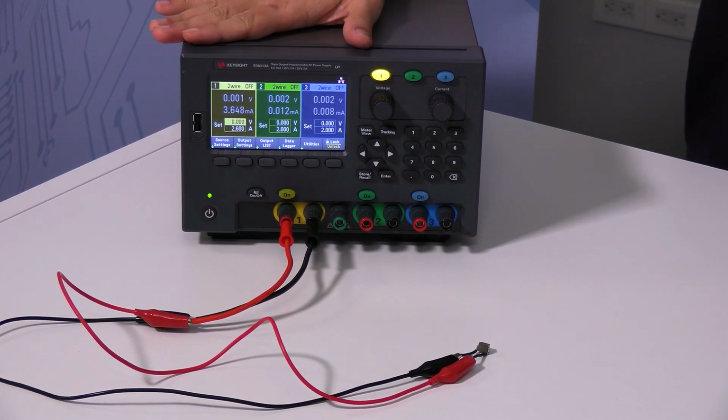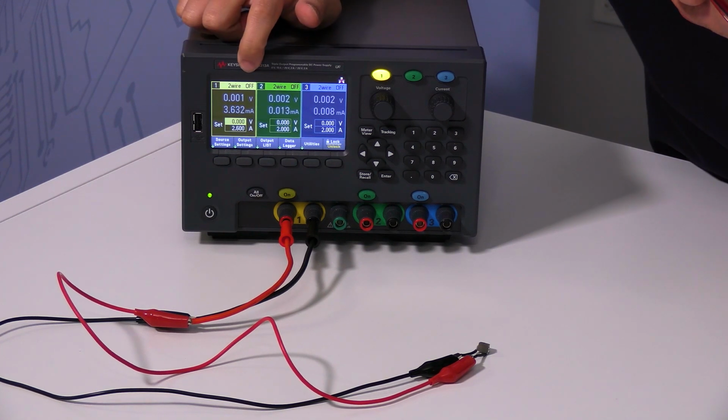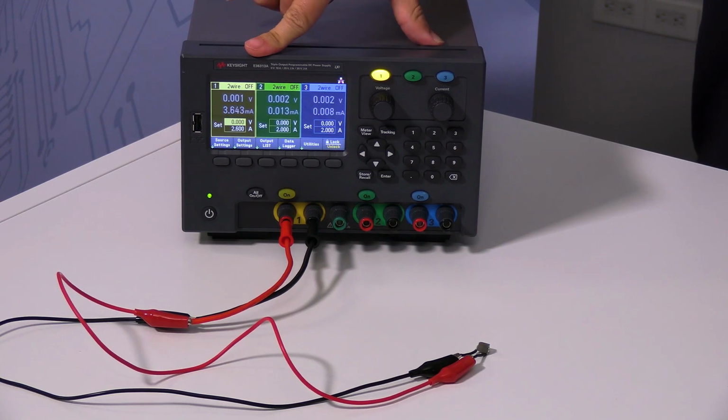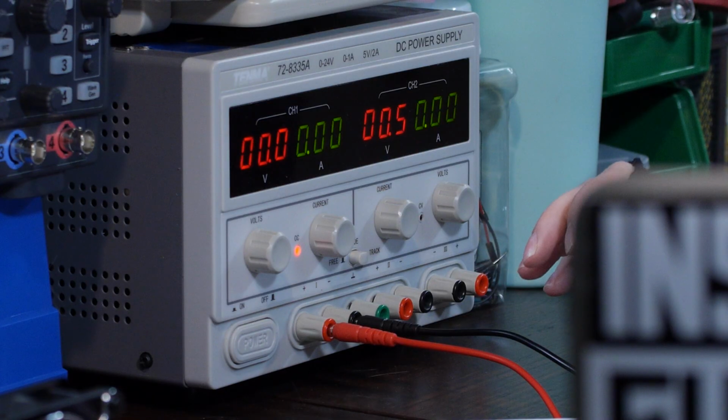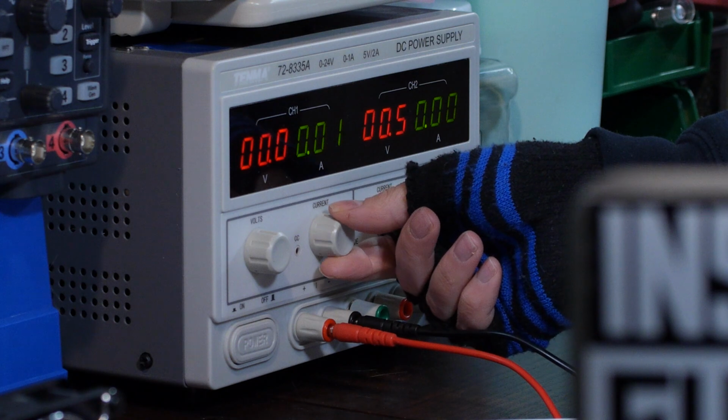And what we're gonna do is slowly crank up the voltage so that we change from CV, constant voltage mode, to constant current mode. You wanna give it a go, Karen? Okay, so my inductor at 340 milliamps will have a temperature increase potentially of 20 degrees Celsius. So let's see if we can make that happen. So I'm gonna see if I can increase my current here.